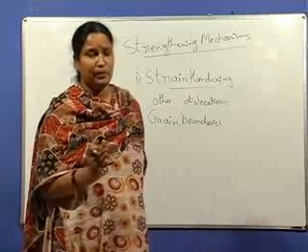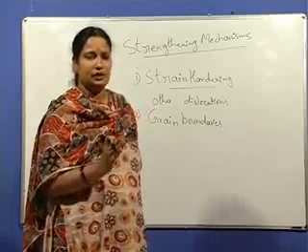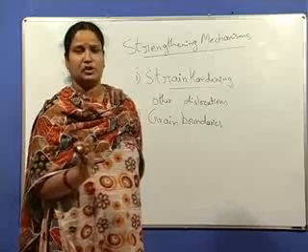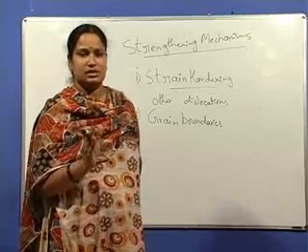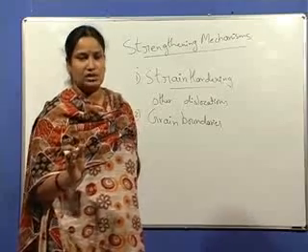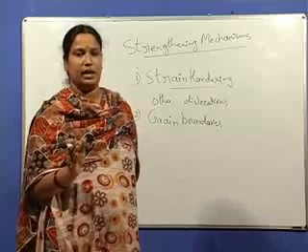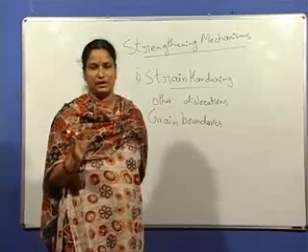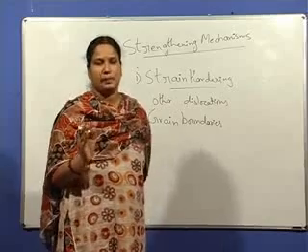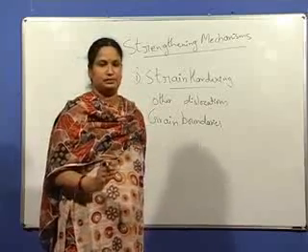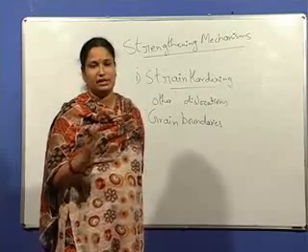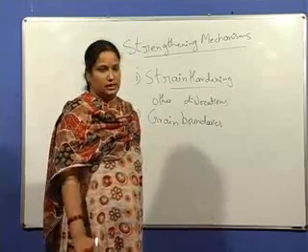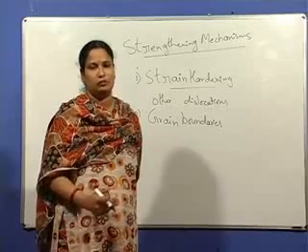Moreover, one of the important relations, which gives a relation between yield stress and grain diameter, was also discussed. That relation is known as the Hall-Petch relation. That is, yield stress is equal to the friction stress plus a constant, the Hall coefficient, that is also known as a locking parameter for the dislocations, times d to the power of minus 1 by 2. So yield stress is inversely proportional to the square root of grain diameter. The finer the grain size, the greater is the yield strength. All this was discussed in the previous lecture, covered under the subheading of grain boundaries.